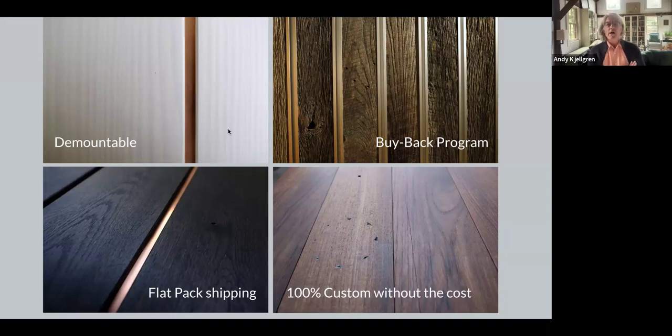Great question. When you're looking at structural timbers, reclaimed wood gets graded and can be graded like any new wood. If you're looking at a 10 by 10 beam for a timber frame house, a lumber grader is going to look at slope of grain, which you have also in reclaimed. They're going to look at knots. A knot and a bolt hole in a lumber grader's eye are basically the same. All that to say, reclaimed wood can adhere to lumber grading criteria, and it does. So that's for structural timbers.